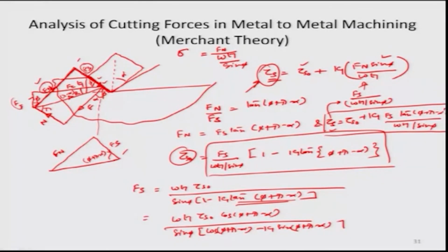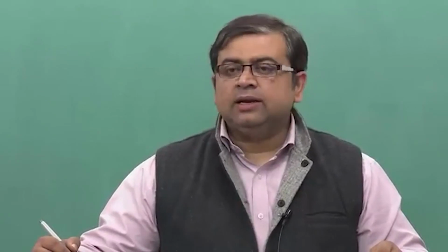So having said that, we now have a relationship where we can use the same underlying logic of finding the cutting force, doing the force velocity product and minimizing it to obtain a final solution, which could be slightly different than the solution obtained earlier, which did not consider the assumption of the normal force. So this brings us to the end of this module 39, and in the next module we will do this force velocity product optimization and try to find out the new angle phi.